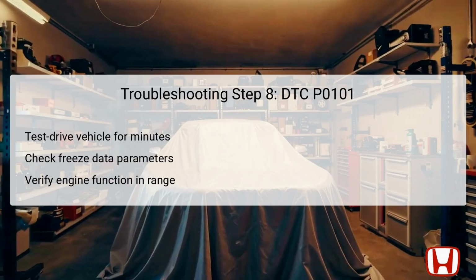The 8th step involves taking the vehicle on a test drive to assess real-world performance and analyze recorded freeze data parameters. During this test drive, maintain a focus on specific factors, including engine speed, vehicle speed sensor readings, manifold absolute pressure, MAP sensor values, and MAF sensor data. These are critical for confirming the health of the air intake system.